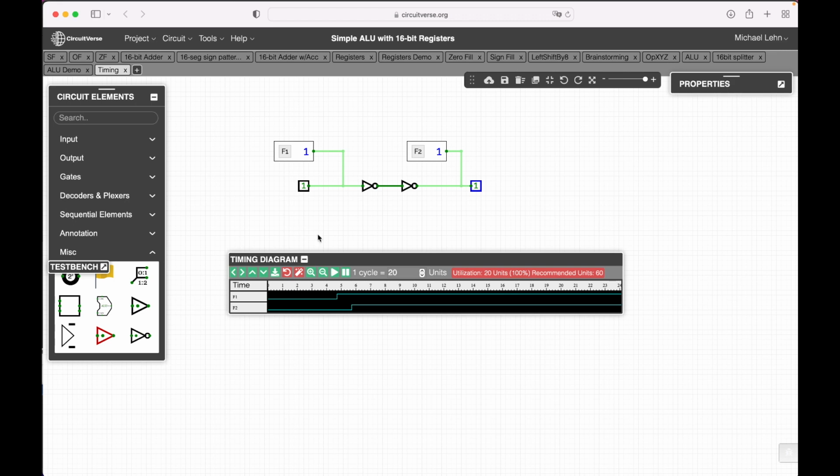And another thing, of course, would be: could there be problems like that our adder is computing some results, storing it in an accumulator, then we want to copy the accumulator into the registers, but maybe this result isn't ready yet? We're still doing the computation and already tried to copy whatever the adder did so far into the register. We would have half finished results. That would be terrible. Now, this lecture will not cover all these issues, but in the engineering department, we have lectures that actually do that.